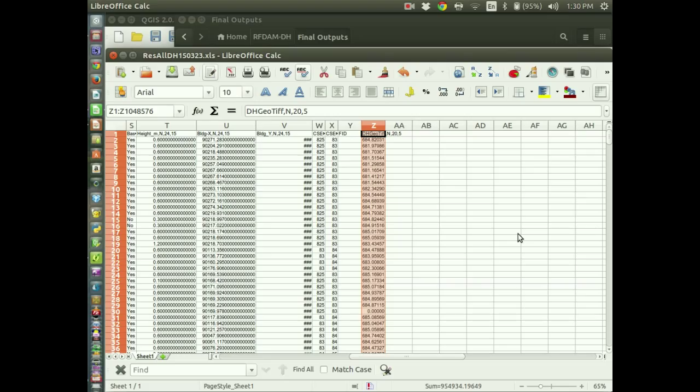And then so you have the two cross sections. And then the last column, which is column 27, is the draped elevation on the DEM. So we take that coordinate point, the XY, and drape it on the DEM. Again, the DEM has to be in the same projection. Normally it's very hard to reproject the DEM surface, so if you had to, you would change the coordinates of the points to fit the DEM, and then drape it. But the two have to be the same. And after that, you can always reproject the points.